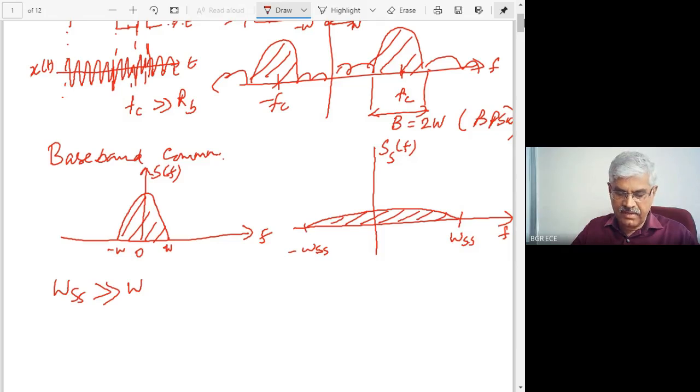So how many times greater? That is for us to decide. So this spectrum is spread over a large bandwidth, but with the same energy. If the highest value here is 1, this may be 0.2 or whatever it is, but it is spread over a large bandwidth. If you spread it and then transmit, it has the capability to reject unwanted intentional jamming or any other intentional activity.